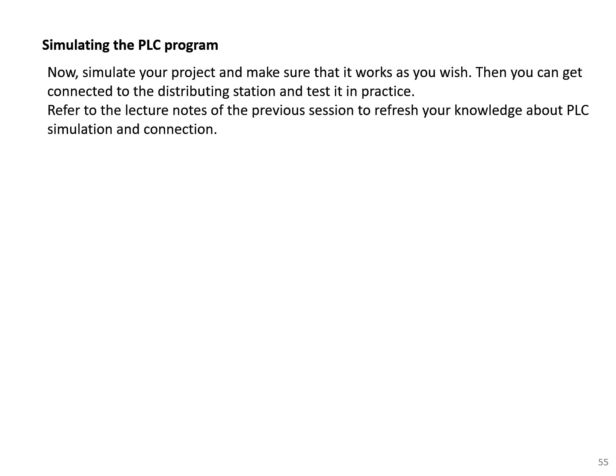Okay, now you have 6 networks. If you have followed all these slides, you should have a complete program. Now simulate your project and make sure it works as you wish. Then you can get connected to the distribution station and test it in practice. You don't have access to the distribution station, but you could do the simulation by PLC sim. Refer to the lecture notes of the previous session to refresh your knowledge about PLC simulation and connection.